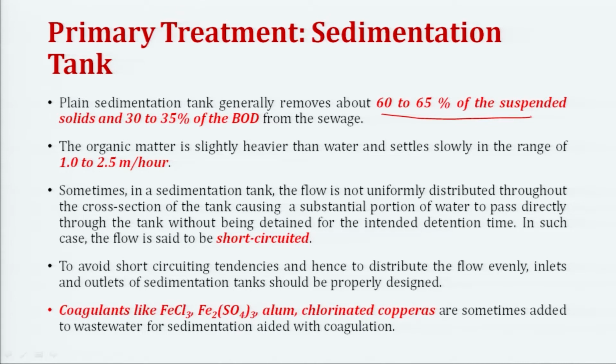So, we are not able to remove 100% of everything, but we are able to remove a huge part of the suspended solids. Why? Because it is suspended. So, obviously, if you keep it for a particular time, then it is going to settle down, and about 30 to 35% of the BOD, which is a good amount, right.